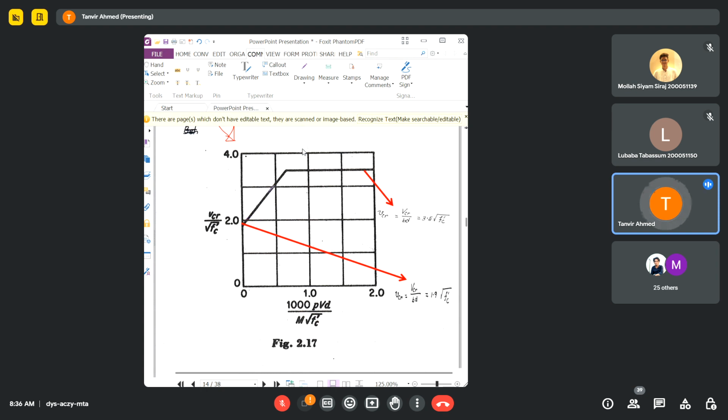And then with the changing of your V and M, you can have different values for your compressive strength of concrete, and this coefficient will become maximum again, 3.5, at a certain point, especially when you have large V and small M, then this coefficient will become 3.5.